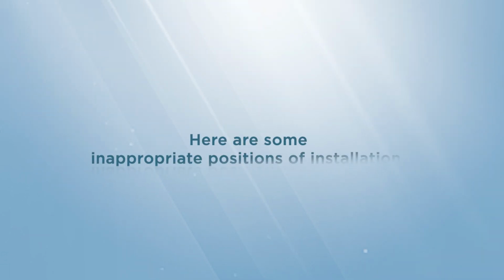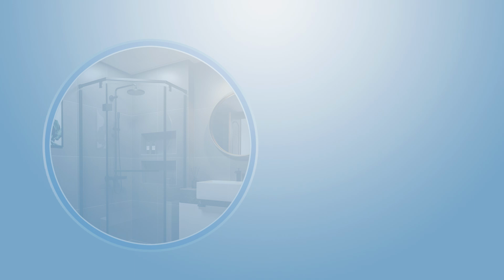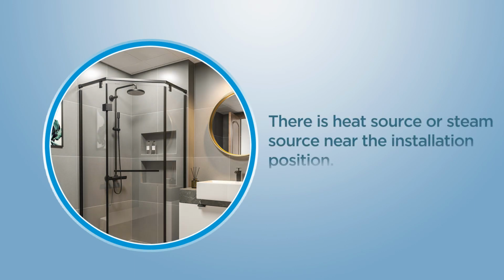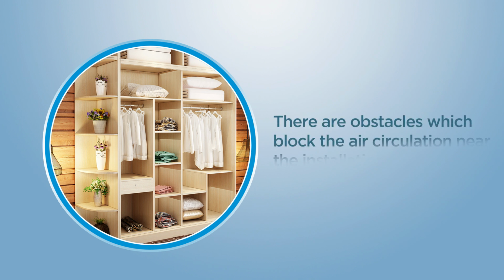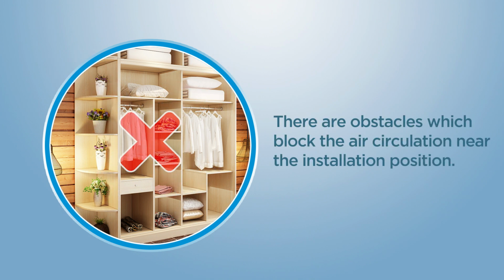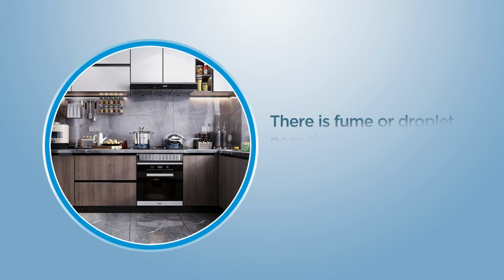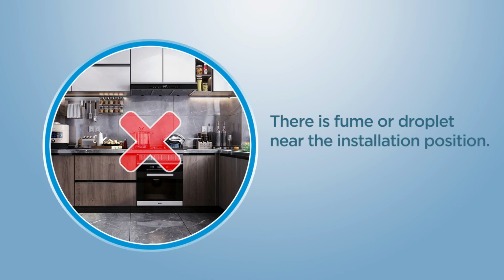Here are some inappropriate positions of installation. There is heat source or steam source near the installation position. There are obstacles which block the air circulation near the installation position. There is fume or droplet near the installation position.